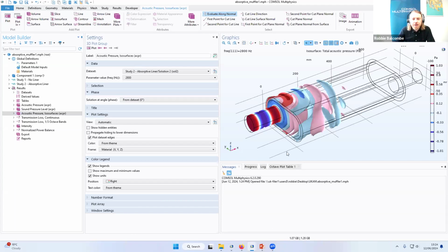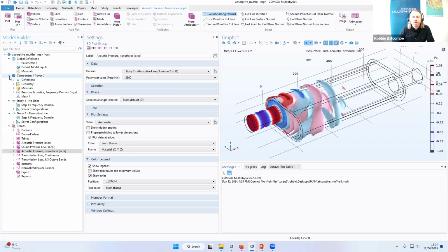The boundary element method, because of it having this dense rather than sparse matrix, when you're solving for problems that are maybe only 1 to 2 wavelengths in size, for example, and you might have a geometry which has quite a complex topology, what you will actually find is that the boundary element method, in terms of the resources needed to compute, can actually be more expensive than using the finite element method for small acoustic problems. So it's only once you get to the mid-sized to large acoustic problems that you will actually see the benefit of using the boundary element method.